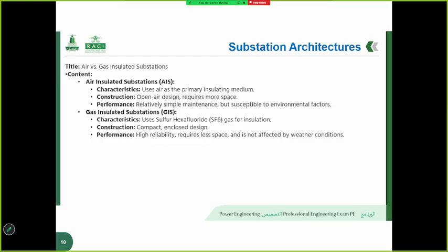Another substation type is GIS. GIS uses sulfur hexafluoride, or SF6 gas, as the insulating medium. The gas is a colorless, odorless, and non-toxic compound with an extremely high dielectric strength, far superior to that of air.